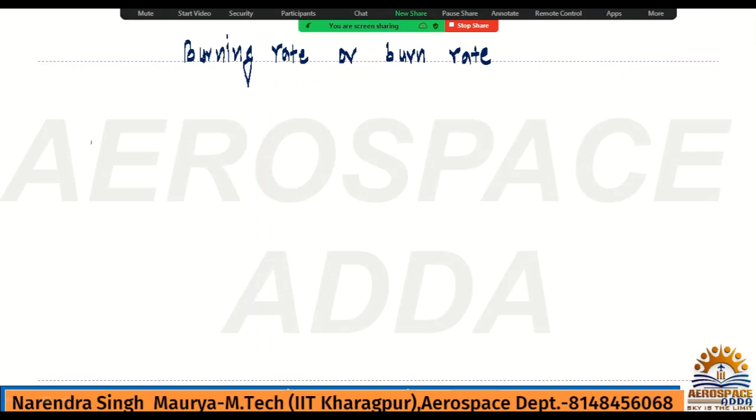Hope it is clear. So the burning rate depends on the propellant composition: at what rate you have added oxidizer, at what rate you have added fuel, in terms of percentage. That is the composition, and there are two types of composition, homogeneous and heterogeneous.